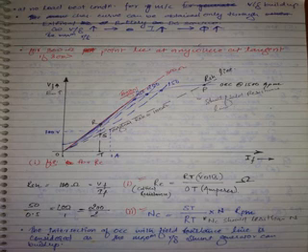So if you observe, according to the definition of critical speed, it is the minimum speed of the generator below which the generator won't build up. Here this is the maximum voltage the machine can build up. Let us say below NC you are rotating the machine. If you rotate below NC, how is the OCC? Below that. So where is point P now? Somewhere here in the residual voltage region. So finally we say at this speed, what is the maximum voltage the machine can build up? Only residual voltage. That itself is the maximum, meaning no build up of voltage. So we are at this critical position. Now within 3 steps, simply you can calculate RC and NC of a given machine.